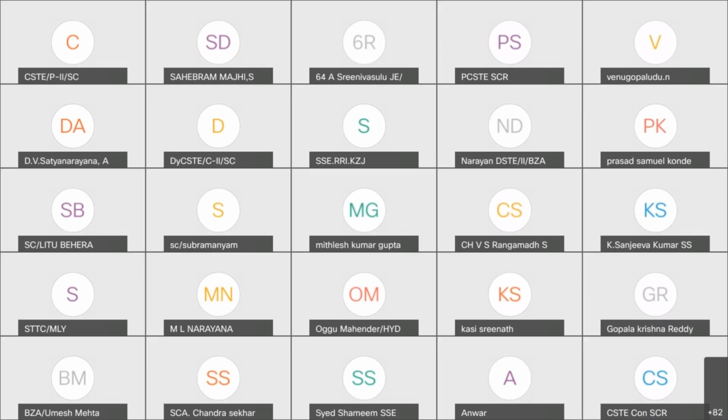In TWS, one more point is that the MS plate which is fixed on the fourth sleeper needs to be widened, sir, for square alignment of rods as well as the throw bar. Also, as per the RDSO drawing, we are unable to install with this design, in my experience. So we are providing 4 more sleeper fixing holes by adjusting 25 mm outwards of the layout, sir. You are not audible in between. Please repeat your question.